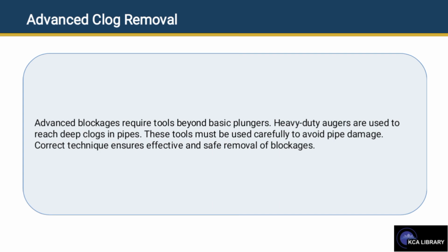Now let's look at advanced clog remover. How do you remove your clog in an advanced manner? Advanced blockages require tools beyond basic plungers. Heavy duty augers are used to reach deep clogs in pipes. These tools must be used carefully to avoid pipe damage. Correct technique ensures effective and safe removal of the blockages.